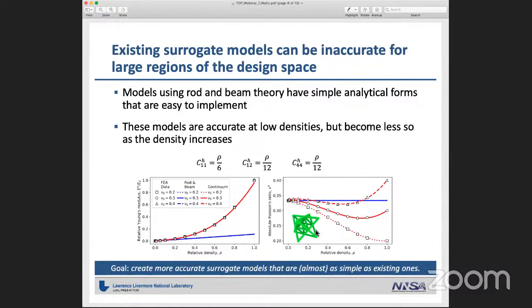They're just points in space where boundary conditions are imposed on the rods or beams. As the volume fraction increases, the size and effect of those nodes becomes non-negligible. In rod theory, you also typically assume that the nodes can't transmit moments into the bars. As the nodes become larger, that assumption becomes less true, and as a result the accuracy of the models decreases.